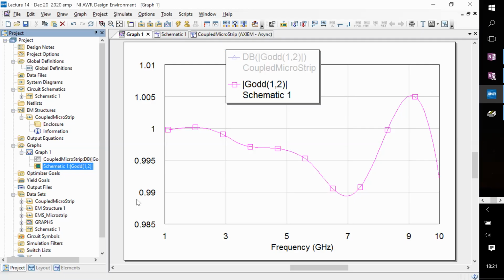Yeah, so that is not possible because a magnitude greater than 1 only happens if you have an amplifier. This is a perfectly passive circuit. So there's no business of any gamma being greater than 1. So this is basically due to some numerical inaccuracies in the computation that you can get things like that.